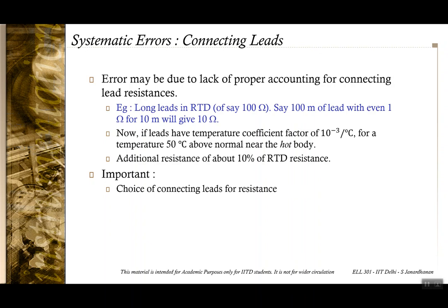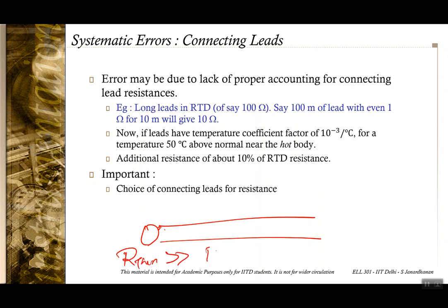On the other hand, this was a case where you have an RTD. Let us say you have a thermistor. If you have a thermistor here and you have long leads, this thermistor resistance is much greater than the lead resistance. So in this sort of case, it doesn't really matter, the lead resistance is not a factor. So depending upon the application, this can be a factor, and it should be taken into account if the application that you have has this problem or not.